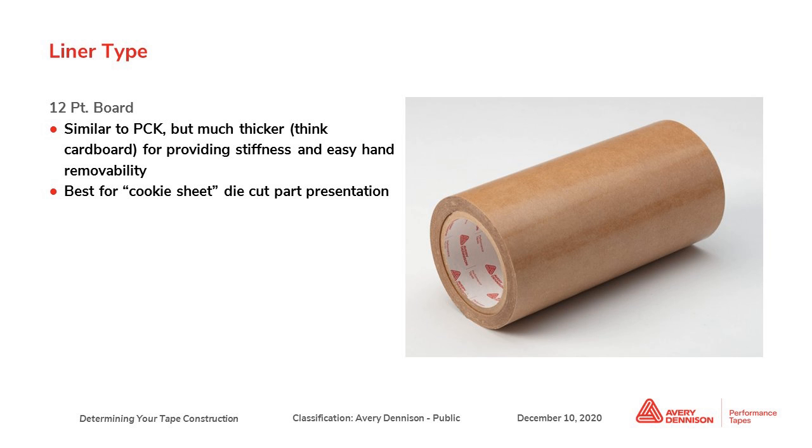That sounds kind of strange if you don't know what I'm talking about, so I'll describe it here. Basically, you could die cut out some small parts. For example, underneath your dining room table chairs, there are felt die cuts stuck onto the bottom so that you can slide your chair around easily on your wood floors. Those would be a felt material laminated with an adhesive. So to make application of those parts easy for the end user, you could cut out 5 by 5 circles of these little felt pads and have them on a larger piece of the liner that's something like 10 inches by 10 inches, for example. It makes it easy to remove those parts and quickly apply them by hand. This could be applied to a lot of applications, especially in automotive and appliances.